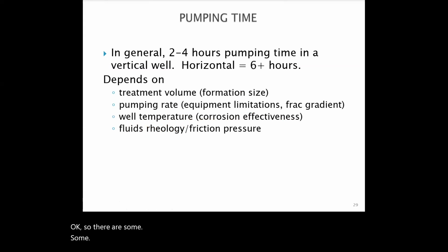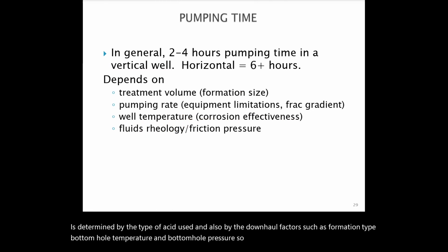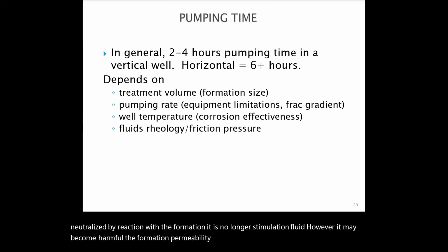Recommended pumping time is something that we need to consider. The time is determined by the type of acid used and also by the downhole factors such as formation type, bottom hole temperature, and bottom hole pressure. After an acid solution has been neutralized by reaction with the formation, it is no longer a stimulation fluid. However, it may become harmful to the formation permeability if allowed to remain downhole.